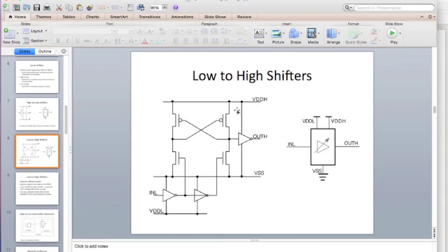So then what you are expecting is this NMOS transistor to kind of overcome the drive of the PMOS. PMOS is turned on fully because it has a full high VDD across it. Whereas the NMOS, when it turns on, has just the near threshold voltage of 200 or 300 millivolts. So for those kinds of conditions, we have a problem with this particular topology, and that's what we'll see later, how a couple of different approaches people have used to make that work.